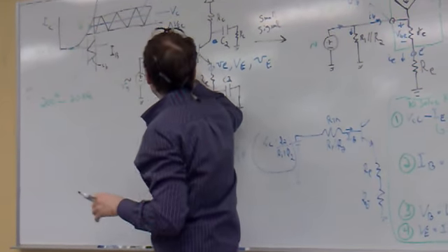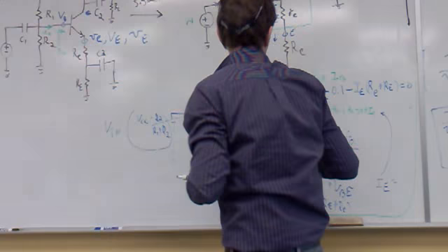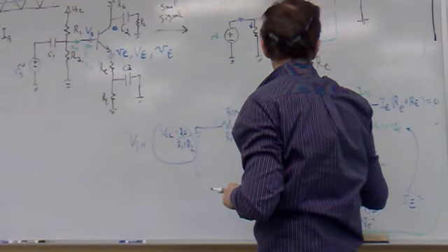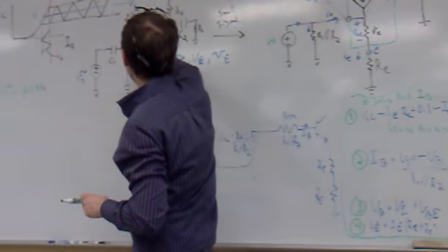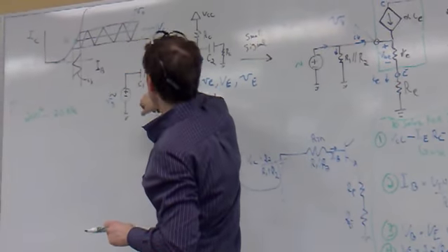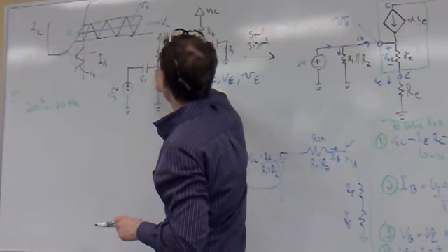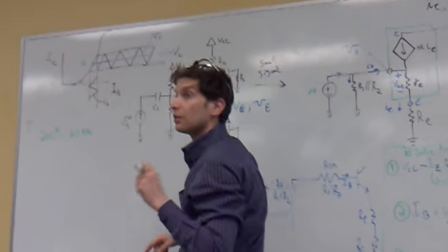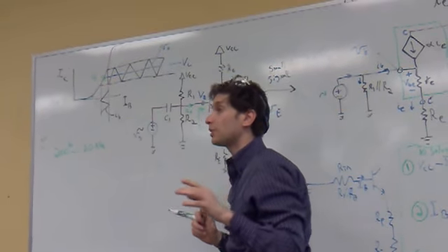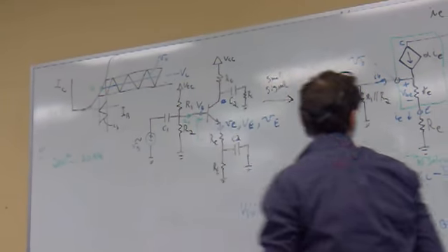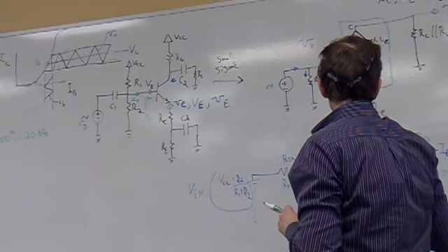So if I assume IB is very small, you have your answer. You can just assume that VB is equal to V Thevenin. If I assume that there's some current being sucked away, that means that this voltage VB is going to be a little lower than R2 over R1. So, if you guys want to get some extra marks, you can actually draw very neatly, so I understand what you're doing. Show me what your VB is going to be.